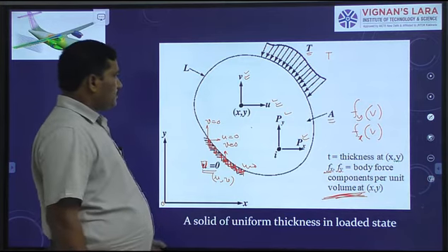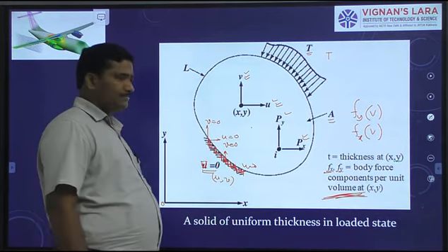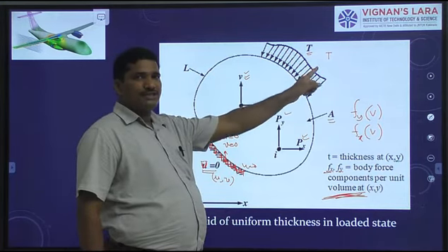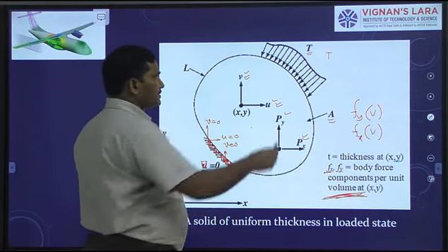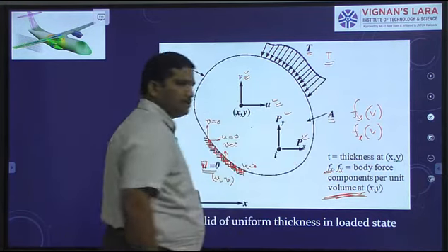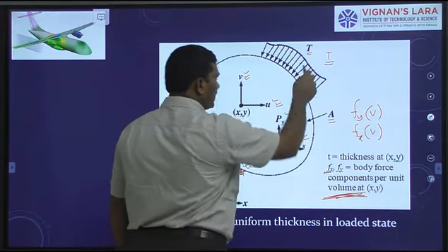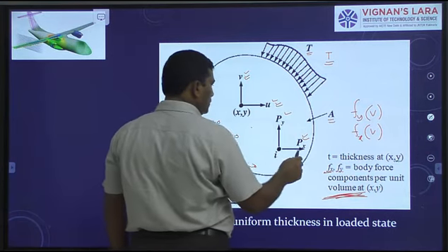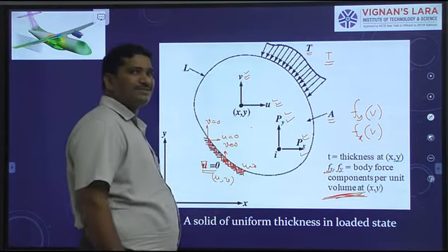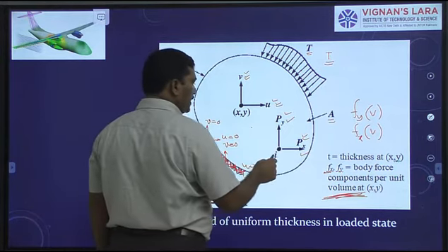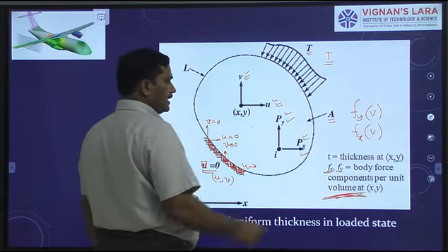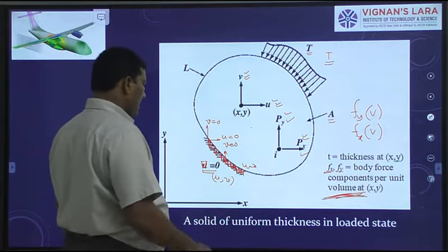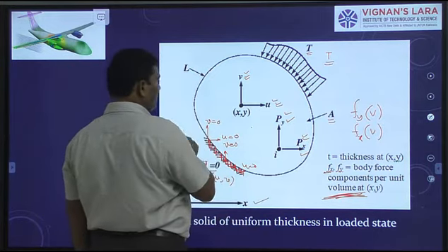Here, what type of forces have we considered? If you visualize carefully, surface traction is considered. It is considered as the force per unit area, where the surface traction is applied on the boundary surface. Now, Px and Py are the concentrated forces applied at point i. Next, Fx and Fy are the body forces per unit volume acting in the directions of x and y.